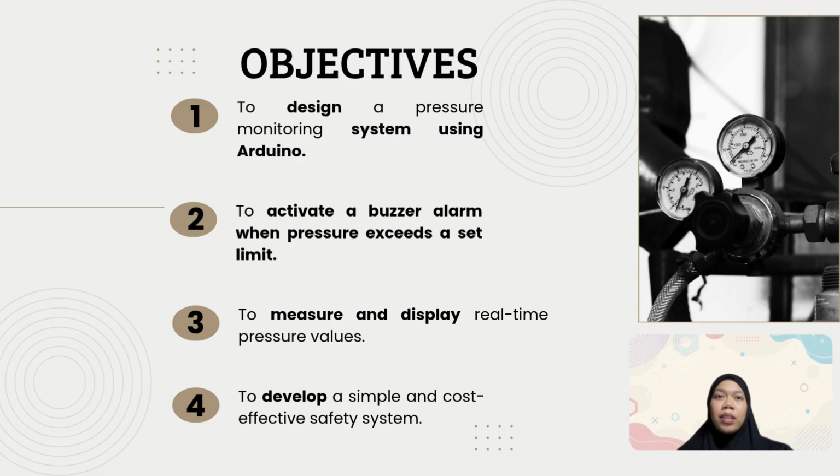To guide the development of this prototype, we established four core objectives. Our first objective, our primary goal, was to design a functional pressure monitoring system using an Arduino microcontroller as our core processor. Second, we aim to build an automated safety response, specifically to activate a buzzer alarm at the exact moment the monitored pressure exceeds a predetermined set limit.